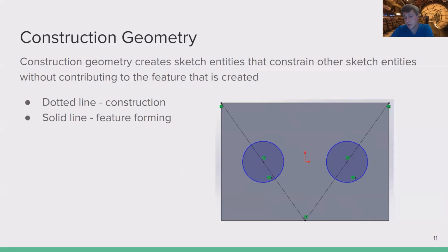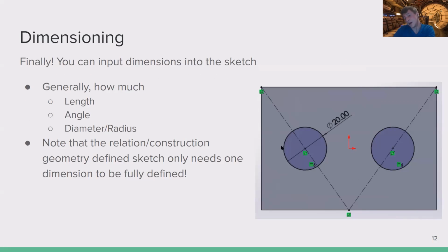When it's blue, when you start modeling, you'll actually get to see this, but you could drag this circle around to make it different sizes. It's a circle, but you could make it different sizes of circle, basically wherever it has degrees of freedom. But if you have a solid sketch, everything is fully defined.